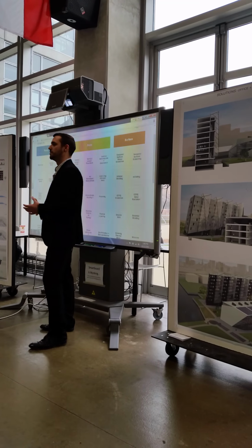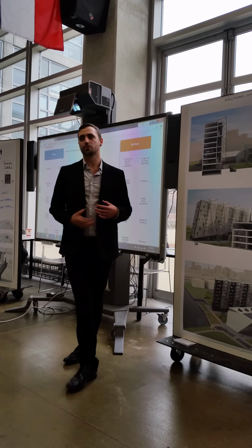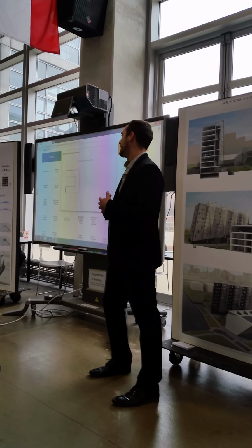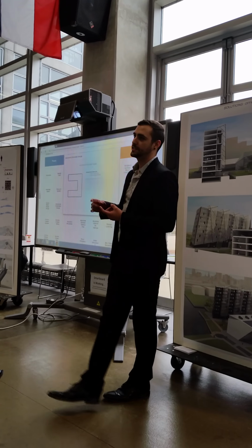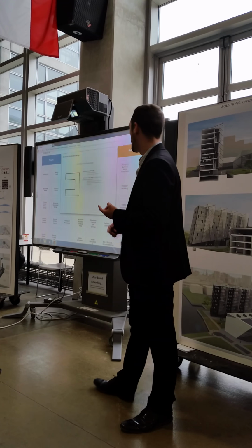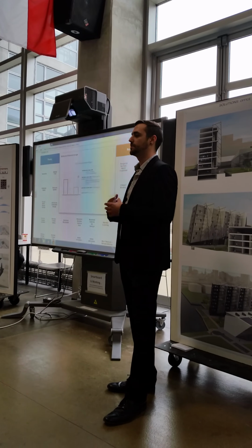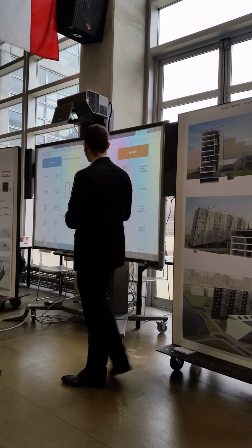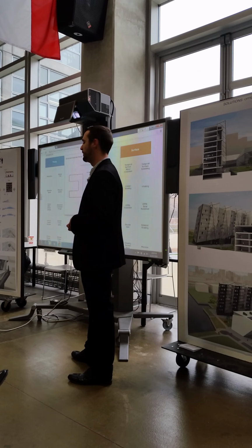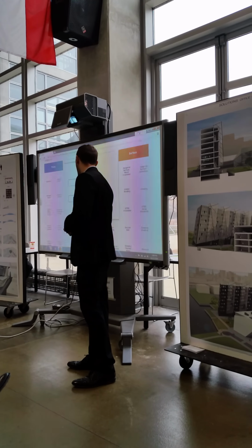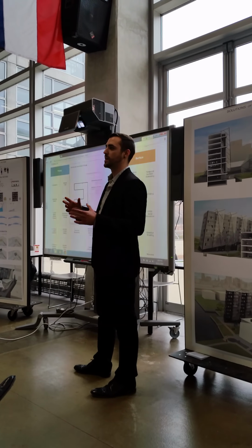So the kind of new way of, or I guess not new, but an alternate way of thinking about how we can design the enclosure systems or buildings around this, we look at enclosure-dominated designs. So that's thinner floor plates that allow for better daylighting and natural ventilation, and maximize the exterior surface area so you can apply surfaces that allow these environmental factors to take place in the cooling and heating of the building. And then also maximize solar orientation and the use of a radiant floor system.